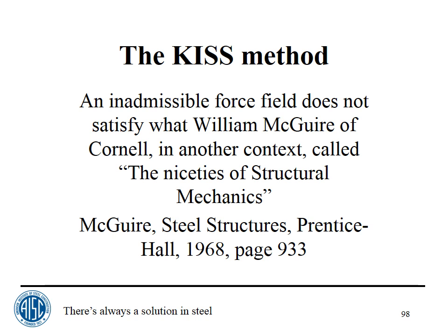I mean, for instance, bolted connections really derive from riveted connections, and riveted connections derive from probably turn of the last century, 1910, 1920, maybe even 1890, a long time ago. And they just tried some things and they worked. On the other hand, welded connections really didn't develop much until after World War II, maybe 60, 70 years ago. And by this time, we understood the niceties of structural mechanics. And so if you go into books on connection design, you find lots of times eccentricities, small eccentricities, 3 inches and what have you on bolts are ignored, but the same eccentricities are not ignored on a welded connection.